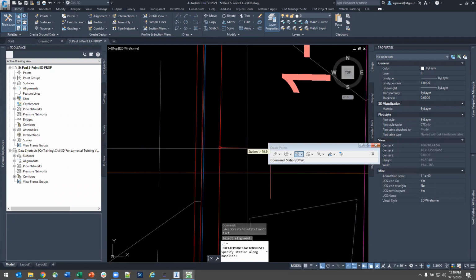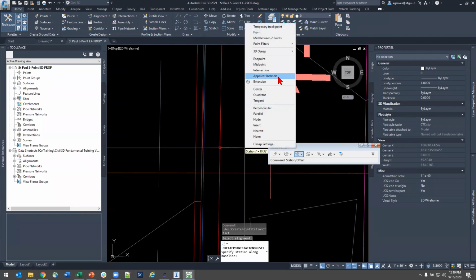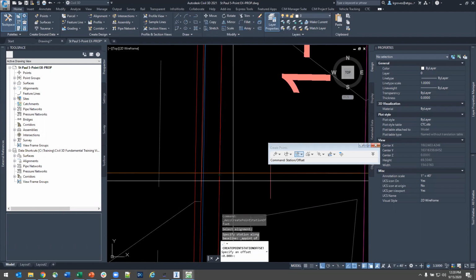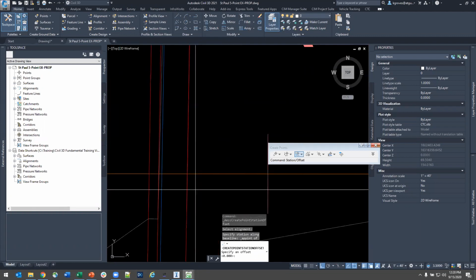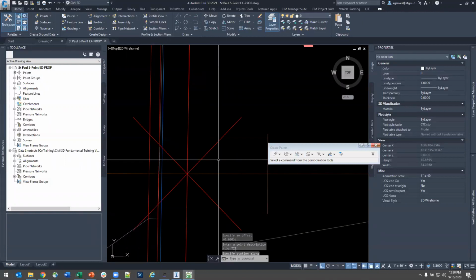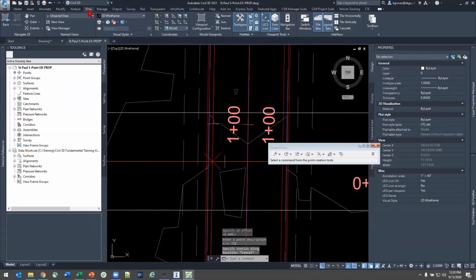Well, now, and for the rest of this workflow, we're going to probably be starting with the apparent intersection subcommand. This is really great for talking to data that share horizontal coordinates, but don't necessarily share vertical behavior. So when I snap out of the intersection of these two alignments, it's going to give me the right spot. I'm also going to not use an offset because I want to be exactly on top of it. We do need to enter a description in here. I like to use something basic like tie. It is completely up to you what you want those to be.